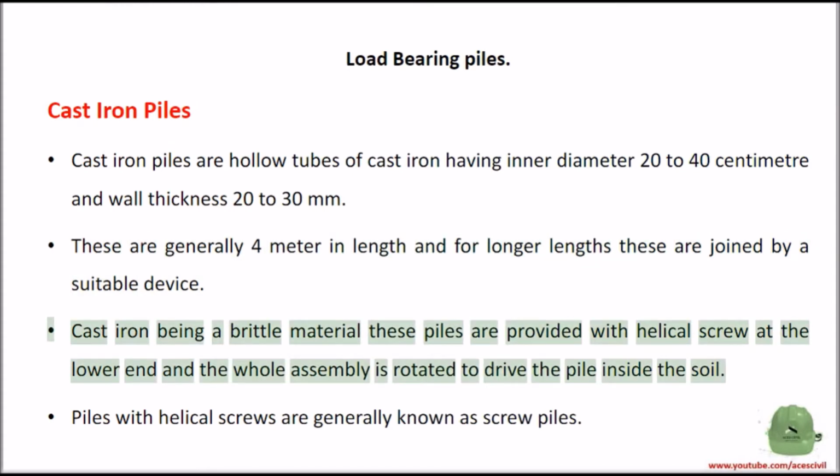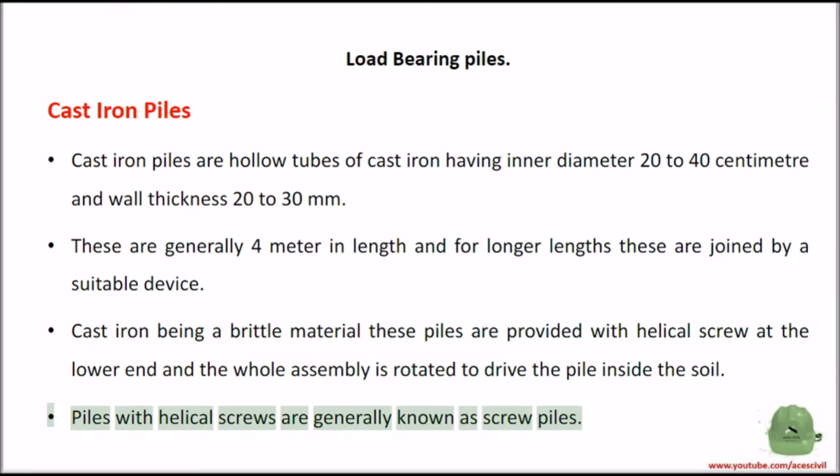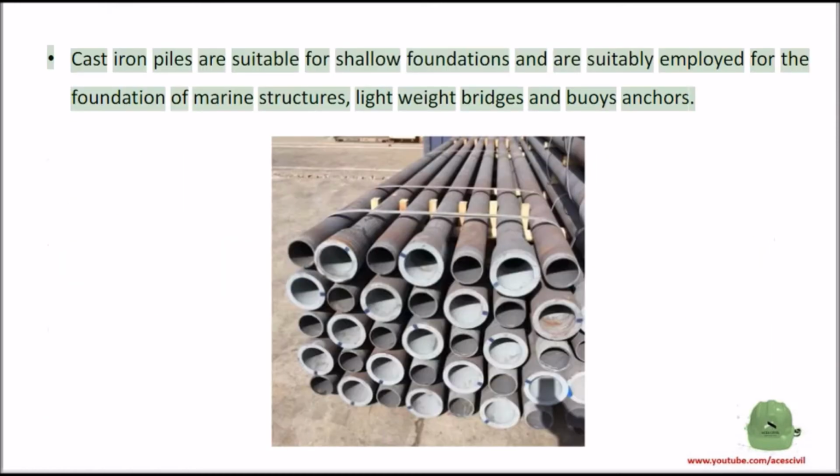Cast iron being a brittle material, these piles are provided with a helical screw at the lower end, and the whole assembly is rotated to drive the pile inside the soil. Piles with helical screws are generally known as screw piles. Cast iron piles are suitable for shallow foundations and are suitably employed for the foundation of marine structures, lightweight bridges and buoy anchors.